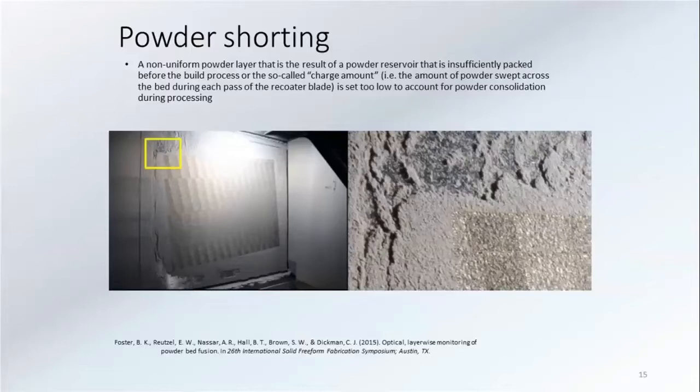And then there's also the issue that once you put the powder into the machine and you pack it in there in the supply feed, as that raises up and it's pushing against it, if you have a large build, that supply will pack down as well. So while the gears moved up 30 microns, because the powder is packing down as it goes along, you might have only spread 25 microns of actual volume across. So there's nuance in there. We typically go 150 to 200% depending on what I'm doing and how big the part is in the machine.